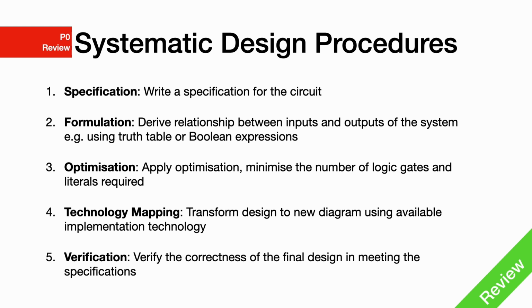Step 3, optimization, is where you transform your formulation into simpler designs, and in terms of using hierarchical designs, if you know what kind of technology you have available to you, optimization can also take into consideration the technology you have. And in step 4, technology mapping, you take whatever it is you have obtained from optimization and use the technology you have to implement them.